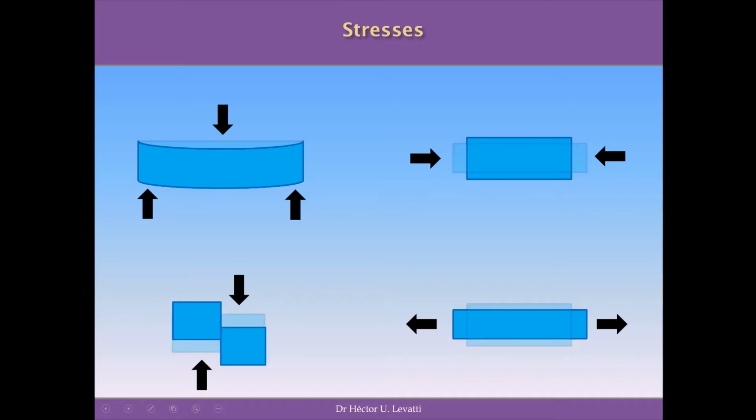After the application of the forces, you will have deformations in your structure. So here we see the deformation produced by these loads. The first case is what we call a bending situation, because this is a simple supported beam and it's subjected to this force which is perpendicular to the neutral axis of the beam, and it's producing this bending, this sagging, that produces internally the internal forces we have studied already: the bending moment, the shear forces and the axial forces if there is any horizontal force.